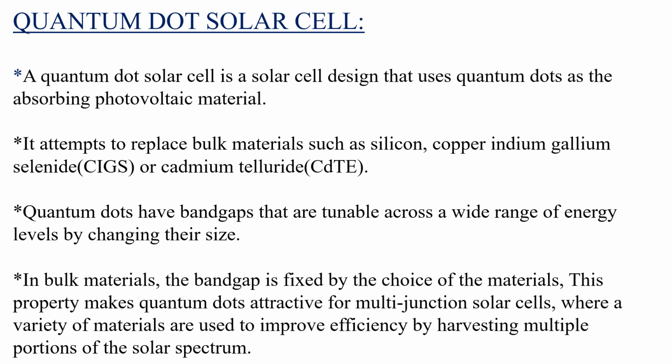In a conventional solar cell, light is absorbed by a semiconductor producing an electron-hole pair. The pair may be bound, and it is referred to as an exciton. This pair is separated by an internal electrochemical potential, and the resulting flow of electrons and holes creates an electric current. The internal electrochemical potential is created by doping one part of the semiconductor interface with atoms that act as electron donors, n-type doping, and another with electron acceptors, p-type doping.